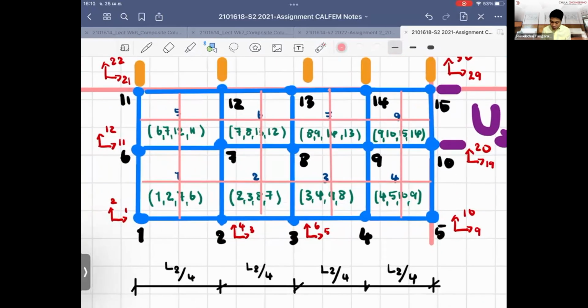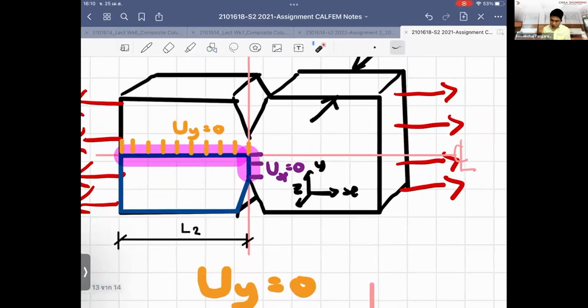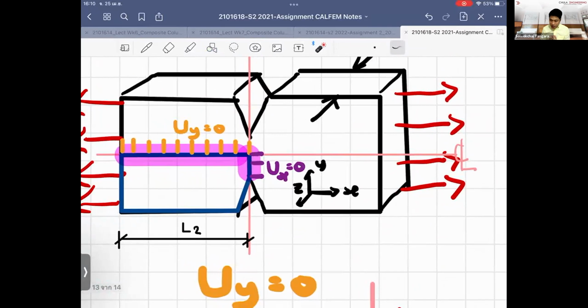For example, I am not satisfied enough. I'm saying that okay, I want to investigate the stress along these regions here. The reason for this is because the theoretical concept says that the distribution of the stress close to the crack tip, this is the crack tip, will generate a huge value of stress.